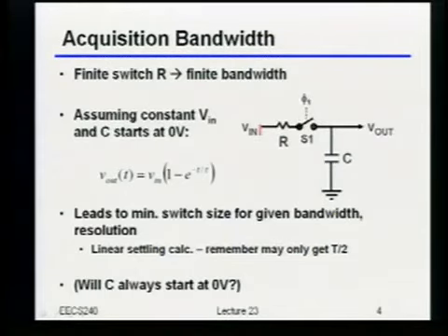All right, just to basically make this tau such that I get a sufficient number of tau of settling during my sampling time. Now you should just be a little bit careful because you may only have half of the clock period to actually do that settling, because a lot of these things work in 2 phases. But basically that's actually quite straightforward. So this should be sort of, again, very familiar to you in terms of how you deal with this. It's just that now you'd have to actually sort of size this switch to meet this settling constraint.